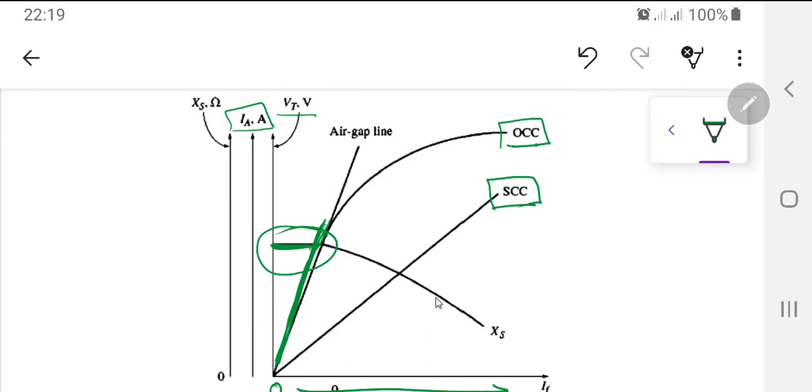But on the other hand, if it is larger, then, as you all know from the phasor diagrams, there is a lot of voltage drop and loss. So practically it's a trade-off, how you adjust whether XS goes to a higher or lower value. You have to decide whether you want safety first or better results from the generator. Certainly for safety, you can have many other relays, fuses, breakers or grounding techniques, which we will discuss maybe when you go into your third or fourth year of the power specialization.